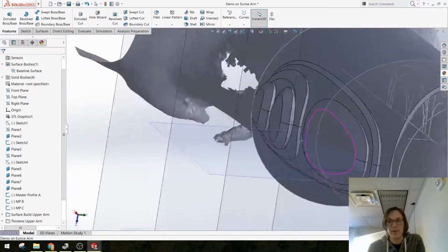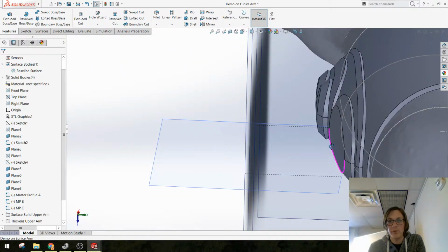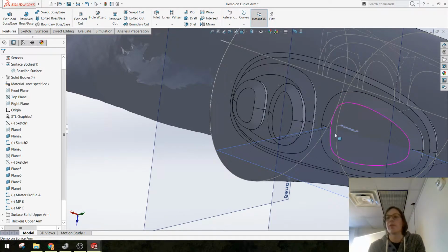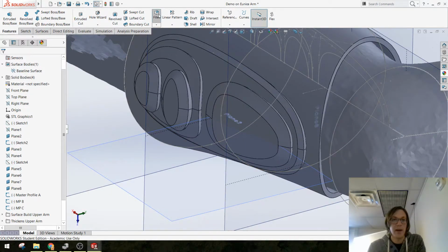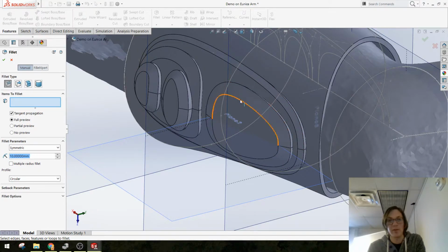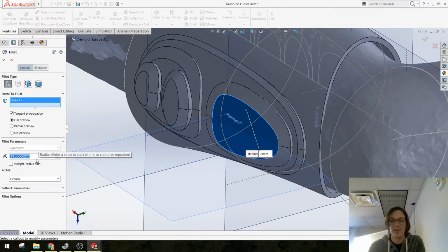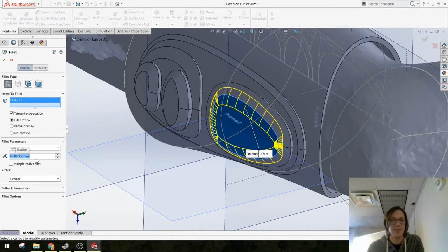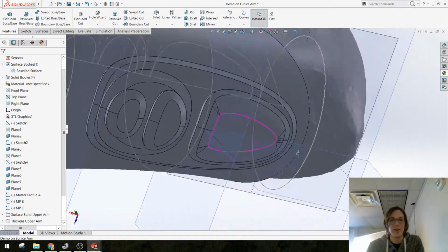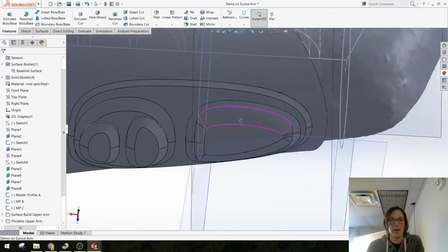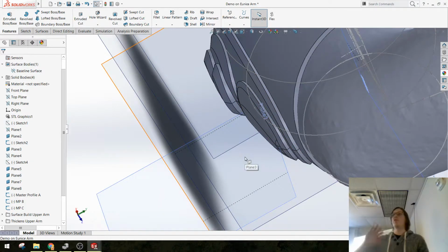One way that I like to do this, so let's say I wanted this piece to look really domed, but I don't really want that like filleted, chamfered look. I don't want that surface. I can go in with a chamfer to taper the edge, and then a really big fillet to kind of smooth it out, like 25 millimeters. No, that's not going to work. Let's try 20. Cool. And now when this renders, you're really not going to see any edge between here, but it will look like this surface is kind of doming out a little bit more than the surface underneath it.